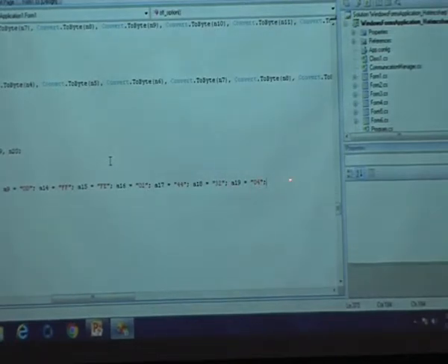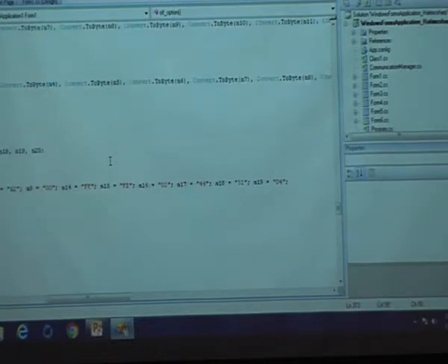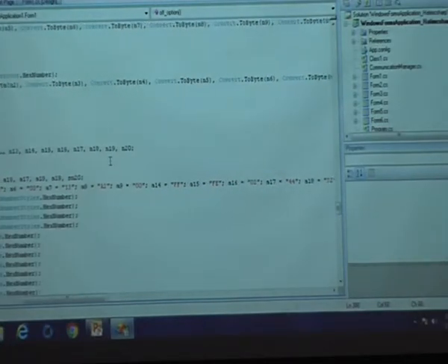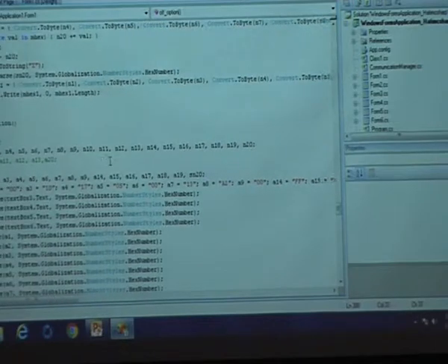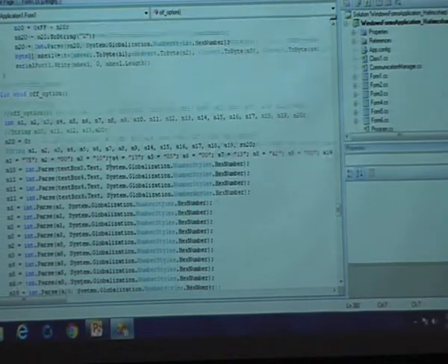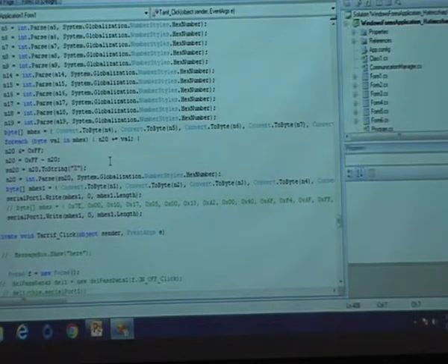04 makes you data output low, 05 makes you data output high. So when you select an off option, you are setting that particular value as 04. It means it should be the off value, and the variables' values are being set through the serial port write. So you are just writing those values to the COM port. Serial port read reads the values from the serial port, write writes the values to the serial port.